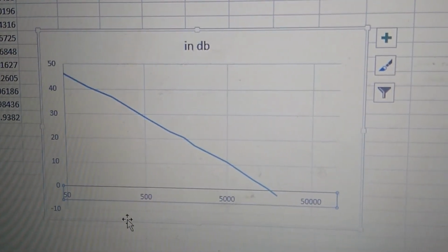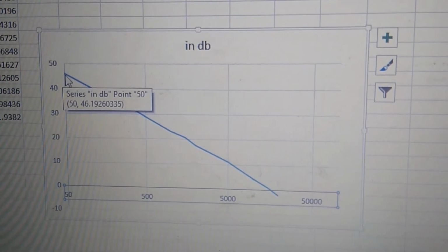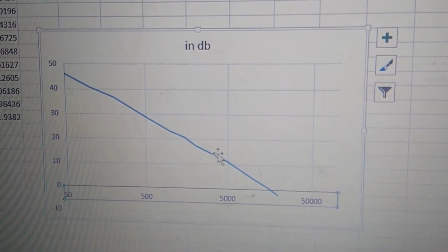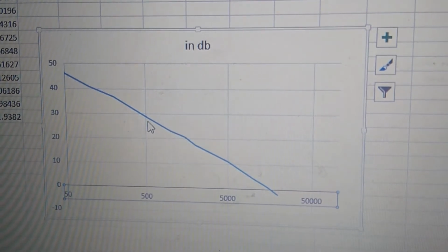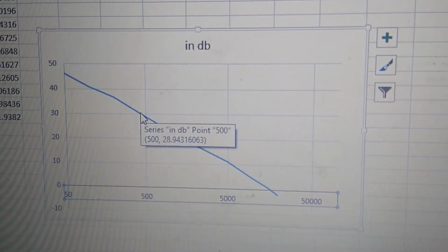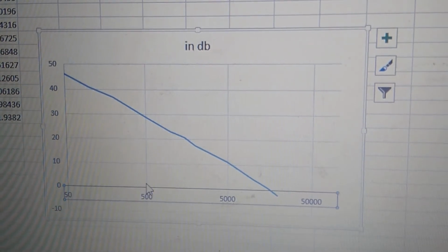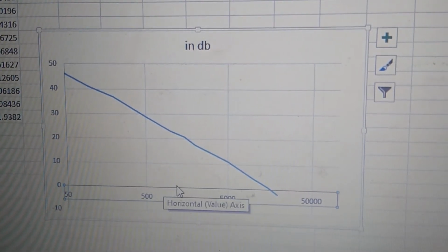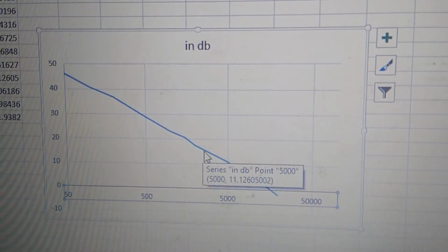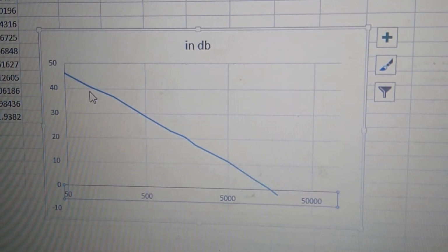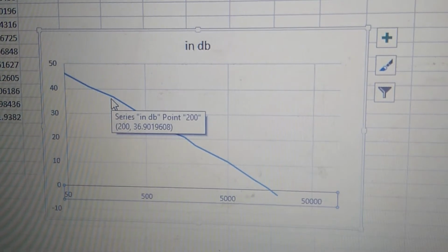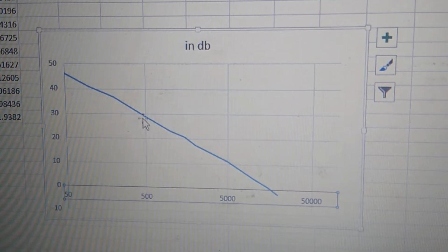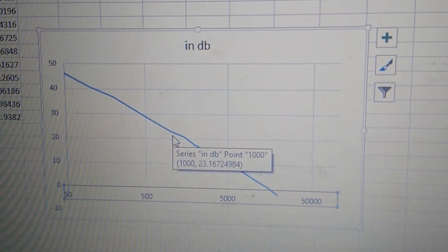Now you see, this is just an integrator, meaning anywhere you are going to get integration. But what will happen if I integrate around 500 Hz? Then your gain will be around 30 only. As long as I am increasing the frequency of the signal, you are going to get a decrease in gain, meaning integration will be happening but the gain will decrease, so it will be acting like a normal RC integrator. There is nothing like an active RC integrator in this one, because with the increase in frequency there will be a decrease in gain. So here our purpose is not fulfilled with your normal RC circuit.